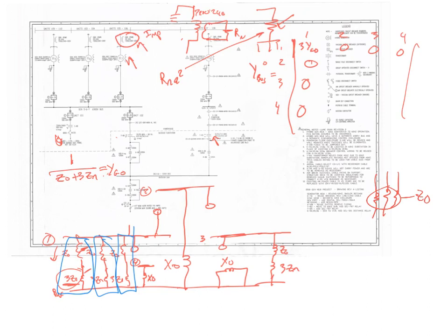I didn't finish my discussion on this, right? Why do we have 3 of those? Because each one of these zero sequence currents is flowing in each leg of the generator, and those all sum to be there. So if I wanted to calculate the actual voltage drop across that Zn, how would you include it?